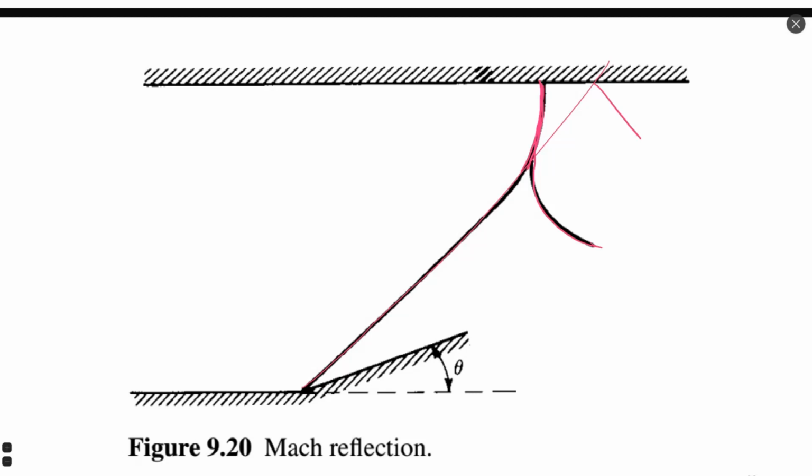We can say that, instead of using oblique shock wave theory on this transition, we can use just normal shock wave theory. We can approximately predict the position of this normal shock wave. It will always be displaced against the flow by some distance. How much cannot be determined analytically, but we know that it will always be displaced against the flow, and we'll have this normal part.